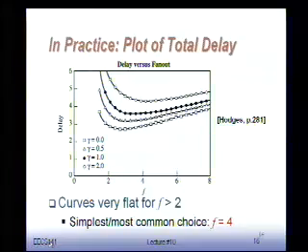Actually, this shows the same deal, but it plots now delay as a function of small f. And as you can see, if gamma is equal to 0, that's no intrinsic capacitance. We see the optimum value is approximately right here, that minimized delay 2.7. If, however, we take gamma equal to 1, you see here, optimum value is about 3.6. But you also can observe that the minimum is very flat. It's not a very steep curve. It's a very flat type of distribution.